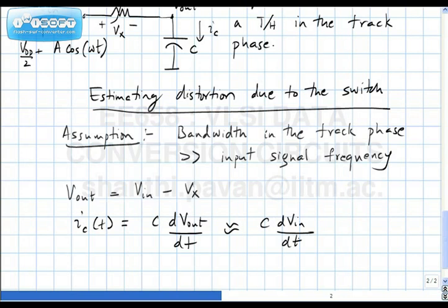And please note that typically, you expect systems to have distortions of 1% and 2% and so on, which may seem like small numbers, but are already too big for a whole bunch of practical circuits. So if you want any reasonable amount of precision, you're always looking at distortion numbers of the levels of 0.1% and so on. So under most practical situations, this assumption will be valid.